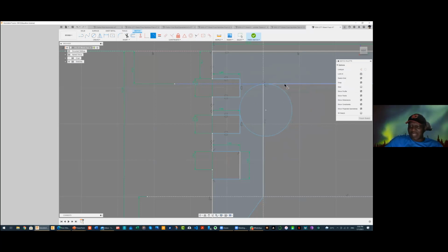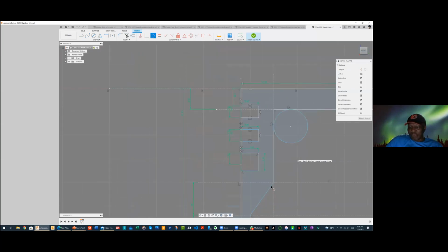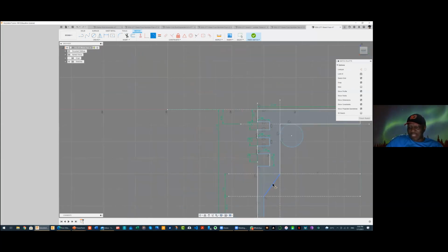So you can see it is there. Suppose I also say I still want this and this to be tangent. So you can see I did that circle, and I've constrained the circle to be tangent to this line and to this line. That is one way. Okay, suppose I want to do a circle, and I want the circle to be tangent to this line and this line, for instance. Or maybe not even do that. Suppose I want the center of this circle to be at this. Okay, let us say I do a circle again.